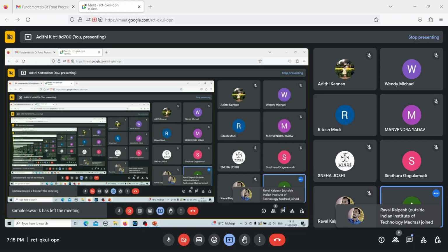So if you remember, N was 1 minus 0.99999 of N0, which is equal to 10 power minus 5 of N0. So that is what I am substituting here. N0 I am keeping same. N is equal to 10 power minus 5 of N0. N0 gets cancelled. We now know what is the D at 130 degrees Celsius, which I am substituting here. So now you'll know the T or the F value at 130 degrees Celsius, which is coming out to be 1.39 minutes, and this is what was asked in the question.